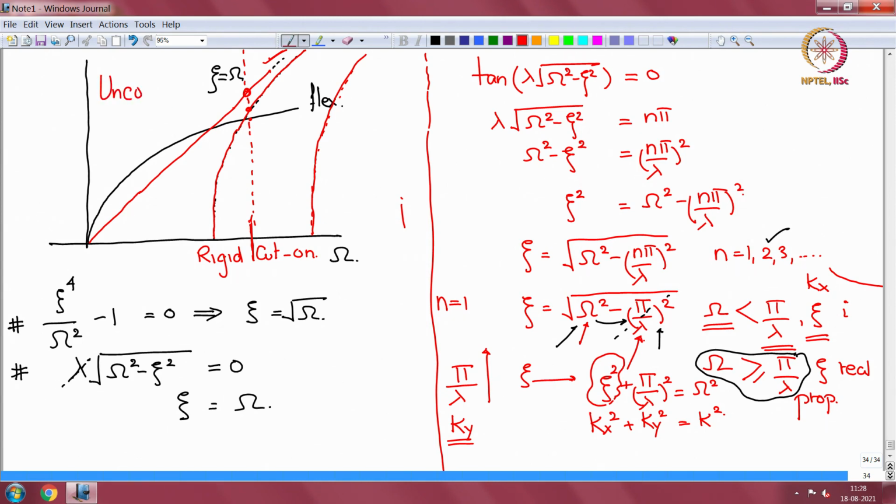We use this language commonly. So, these are uncoupled, that means actually when there is a plate vibrating there is no fluid. So, these waves should not be there, okay, because it is uncoupled. Similarly, when these plane wave and higher order cut-ons are there, there is no flexible wall, the wall is rigid. So, this curve also should not be there, but we use this language. Okay. We plot both of them on the same plot and look at their relationship.